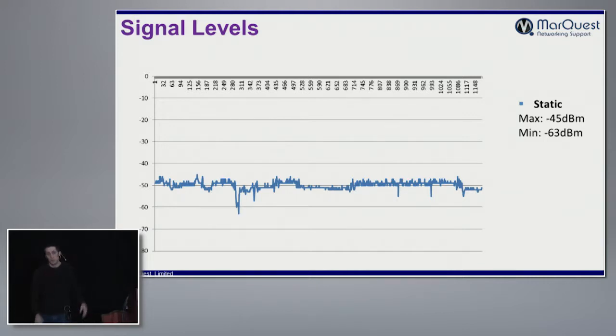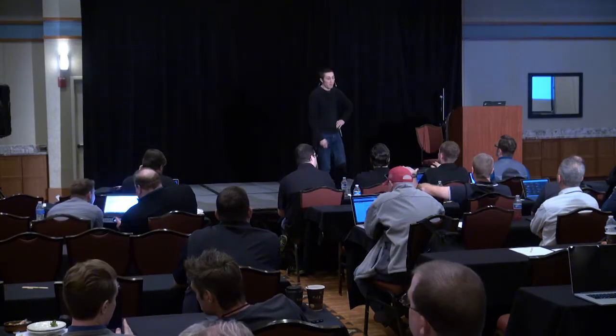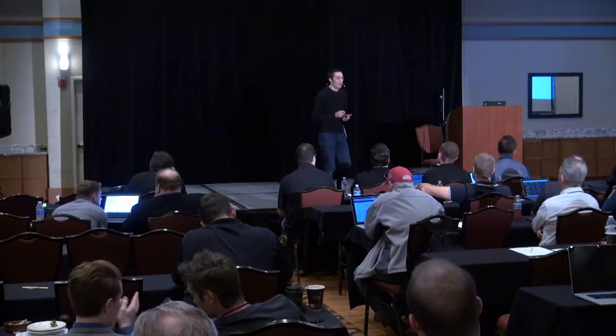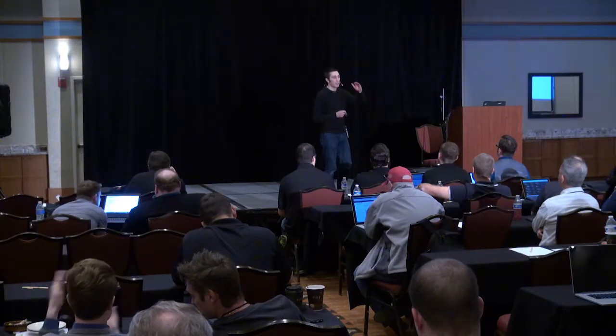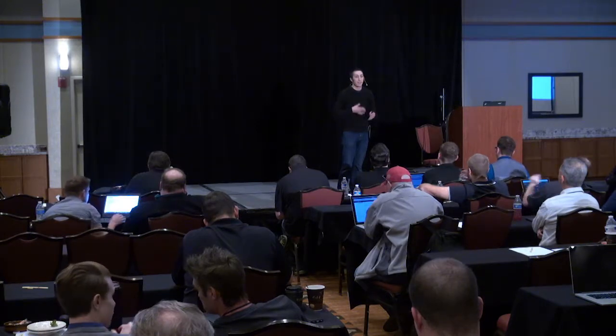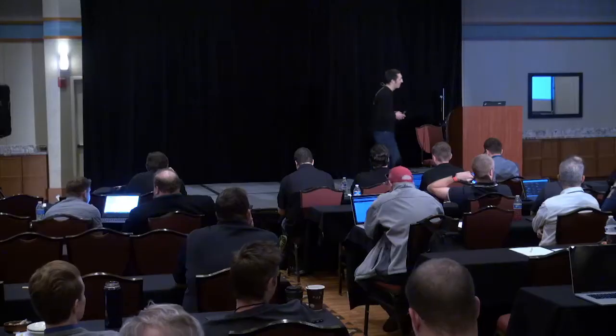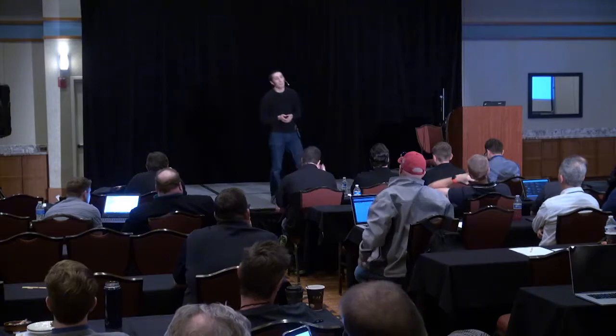So, do you think you would see that difference if you had cabled an AP radio directly to a client's radio? If you actually cabled the two radios together... What, with a piece of coax cable? I don't know. It's not something I've tested. I think primarily it's multipath, yeah. Okay, so if you cabled them, you'd expect it. If you cable it, I would suspect you'll get some variation, because of what we just said about how they perceive signal strength, and there's an inaccuracy in how they measure signal strength for each client. So I still think you'll see a variation, but probably not as much. Have you tried that outdoor? I haven't tried it outdoor, no, but it's a good test.